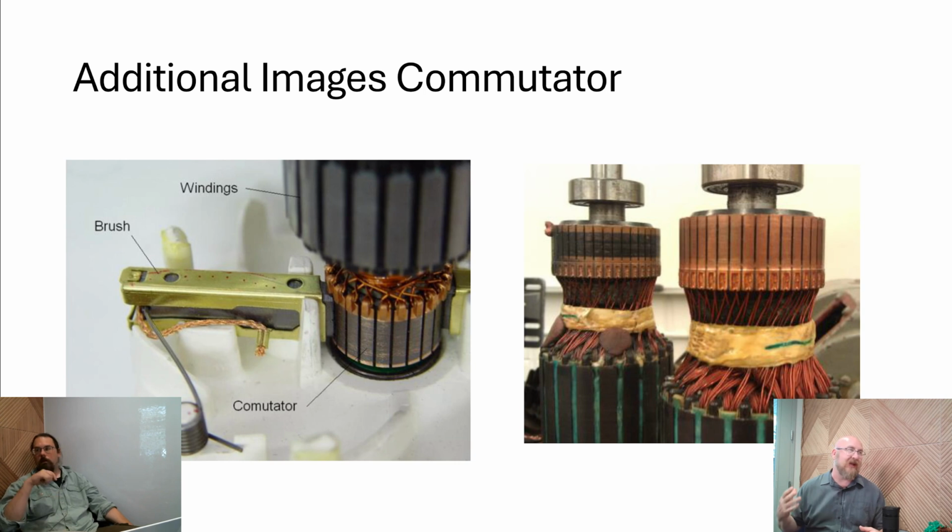When we refer to a DC motor, we're just talking about what we're putting into it. It uses this device right here, a brush and a commutator, that alternates the polarity, flipping it back and forth. We're creating an alternating current inside of the motor. And it's not a sine wave, or any of those things that you assume with alternating current. It's more of a pulse, back and forth.